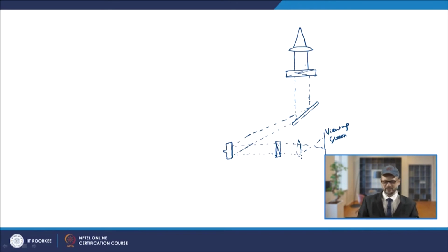The plane polarized light passing through that affected photo stress material is changed into two mutually perpendicular components, parallel and perpendicular to the direction of the stress. Accordingly, you will see these on the viewing screen.